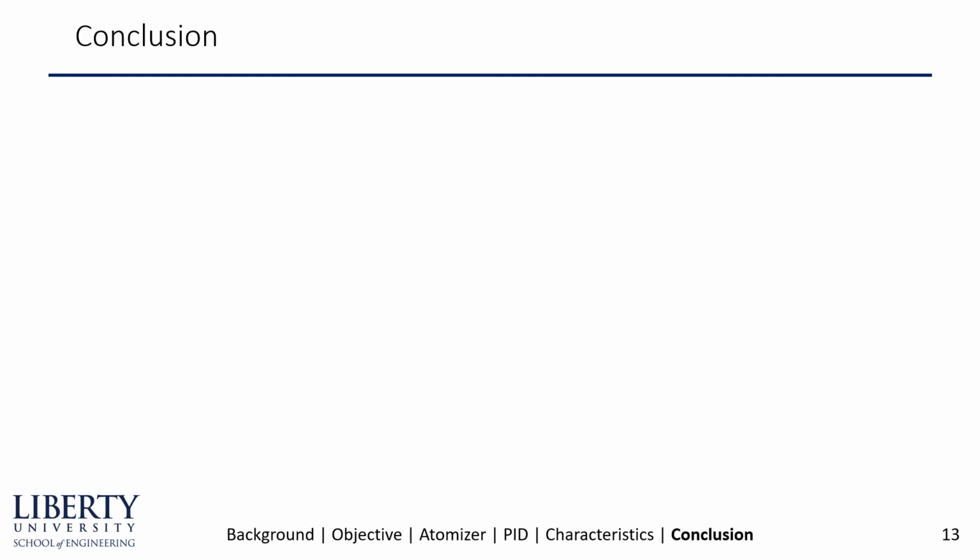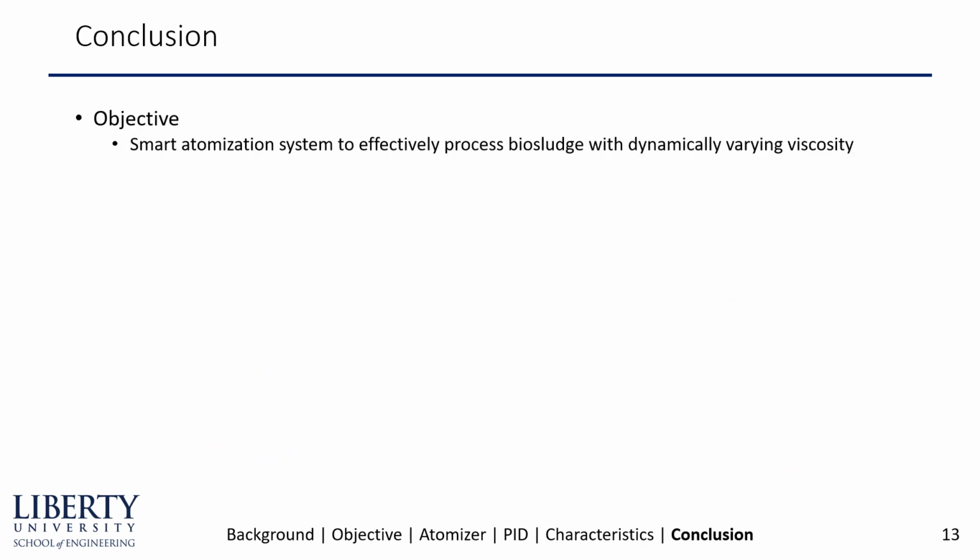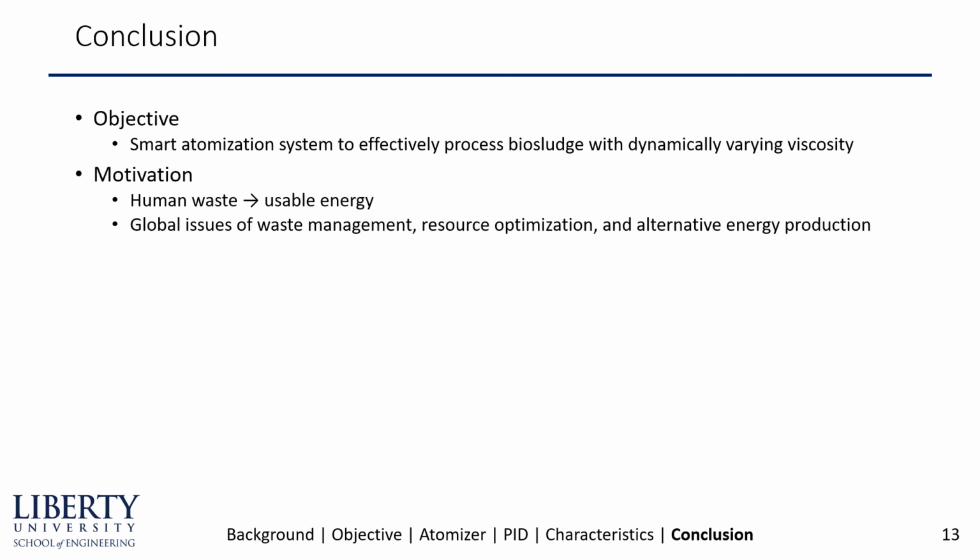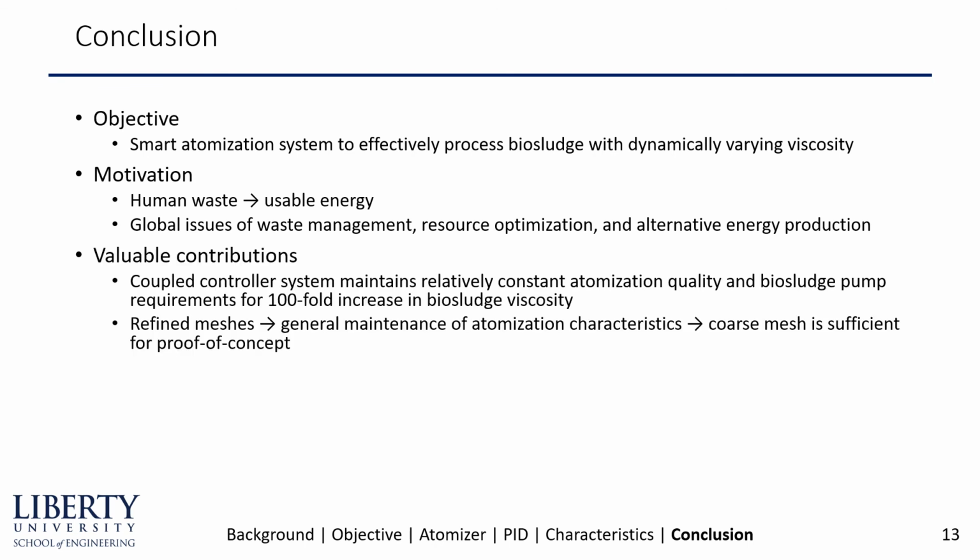In conclusion, our objective is a smart atomization system to effectively process biosludge with dynamically varying viscosity. Our motivation is conversion of human waste to usable energy, addressing major global issues of waste management, resource optimization, and alternative energy production. Our valuable contributions are showing that a coupled controller system maintains relatively constant atomization quality and biosludge pump requirements for a 100-fold increase in biosludge viscosity, and that refined meshes generally maintain atomization characteristics, so our coarse mesh is sufficient for the proof of concept.